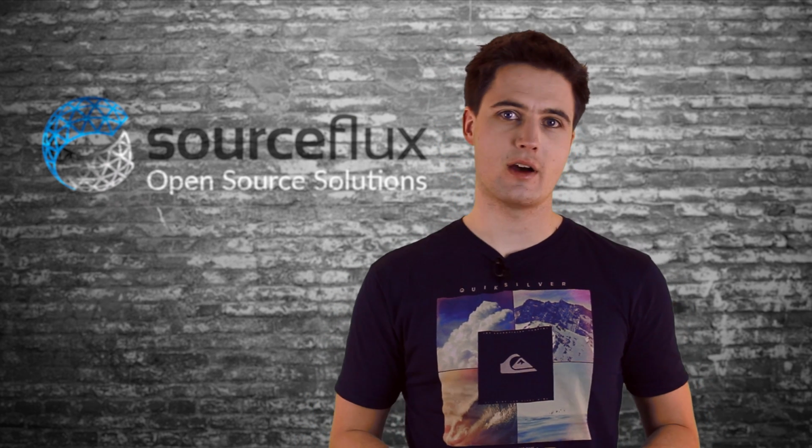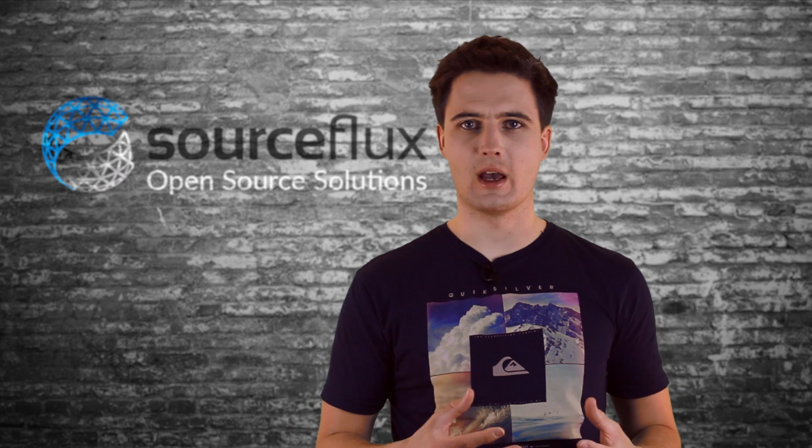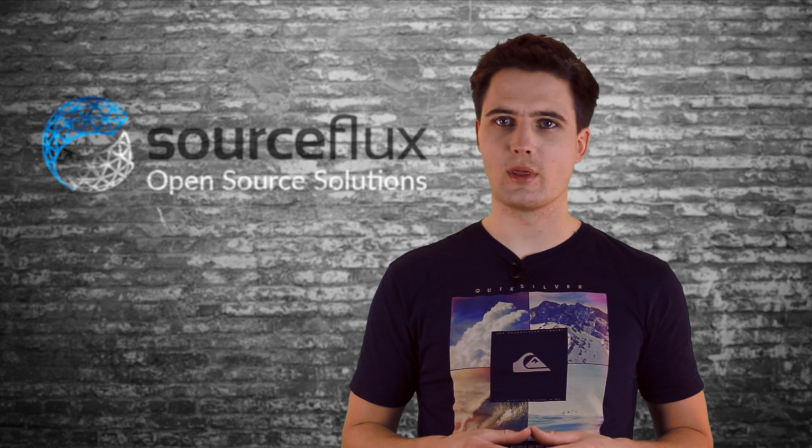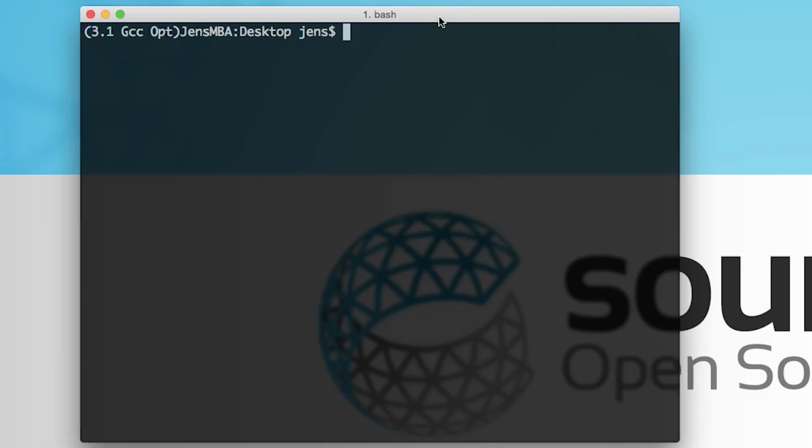In my case, Safari has already extracted the archive and I don't need to do it by hand. You might have to do it though, depending on your operating system. After this preparation, I open up a terminal and jump into my run directory, which is simply done by entering run and hitting enter. I copy a tutorial that is already present in the OpenFOAM distribution so that I don't have to recreate the entire case structure manually.